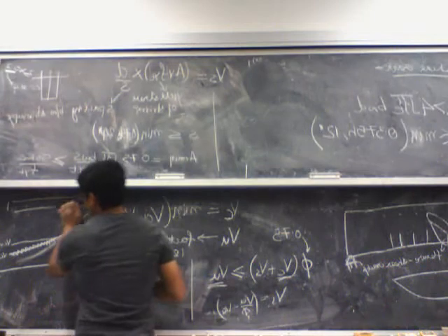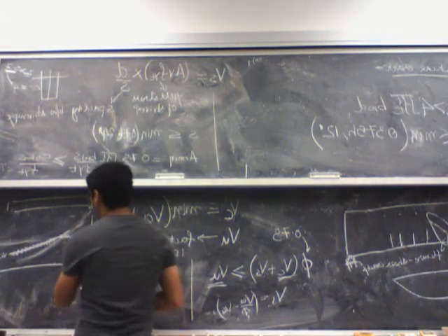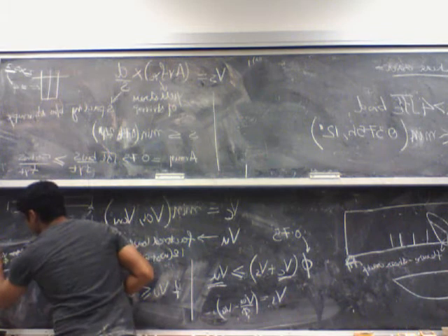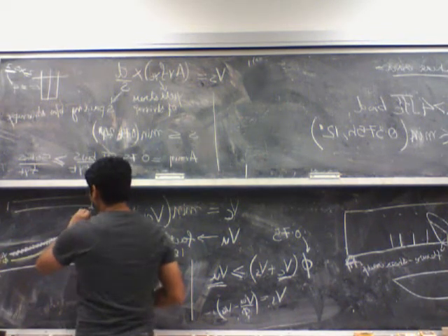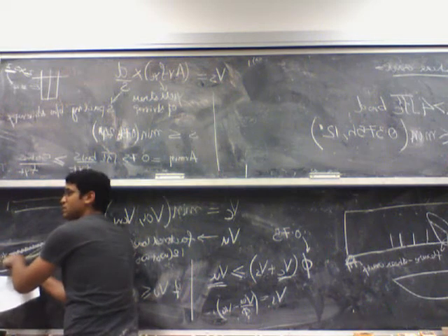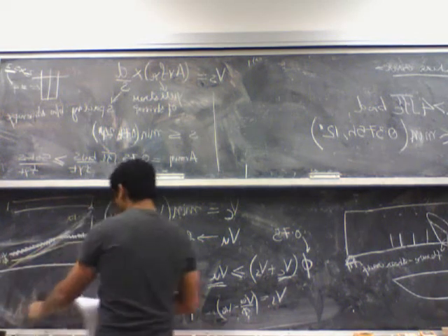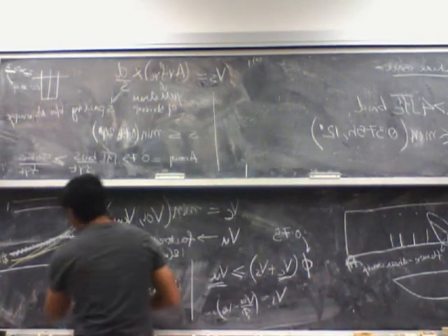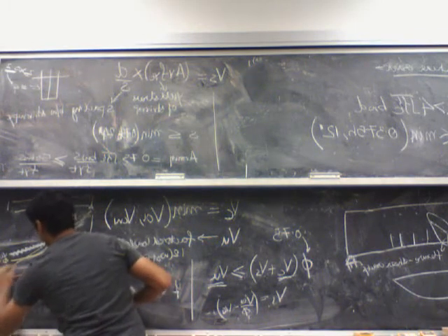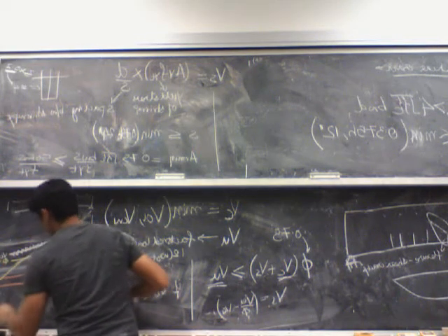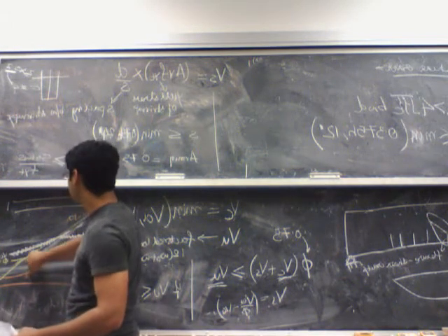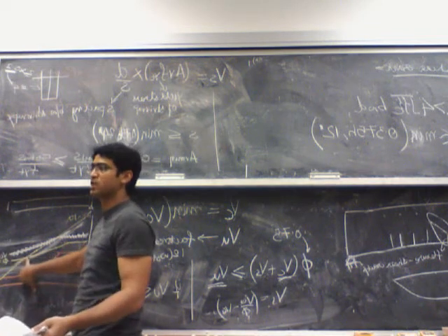So let's say this is my VC, and this is phi times VC. If this is my VU, even though technically my VU is less than phi times VC, you cannot still say that, okay, I don't need to provide any stirrups. What ACI is saying is, within this range up till this point, since your VU is greater than phi times VC, you have to provide some stirrups.